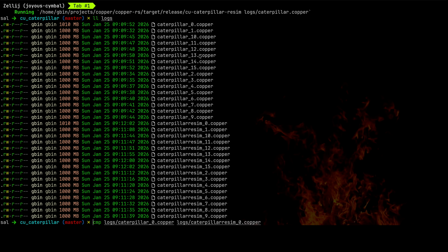So yeah, you see what it means now: determinism. Every time you re-execute and replay one log, you always have the same result. So you can basically be sure that even if you store those logs in a collection of snippets you want to replay, because you want to have those corner cases for your robot ironed out, when they are green, they will always be green with the same code, of course.